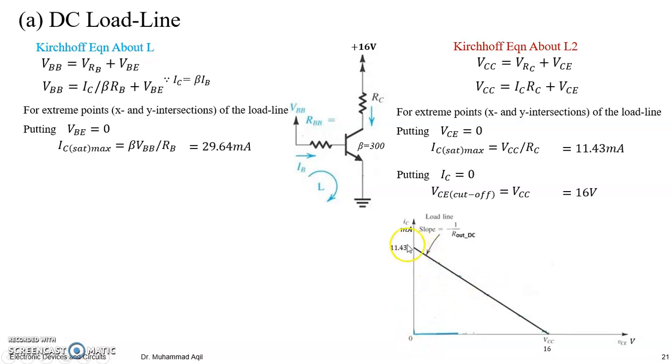This line is just saying that you can operate your transistor only when this line and the characteristics curve have an intersect. So this is just a hypothetical line, but obviously all other points on this line which also satisfy the characteristics curves of the transistor are your desired points. That's why you use this point and also this point to draw the line, right?